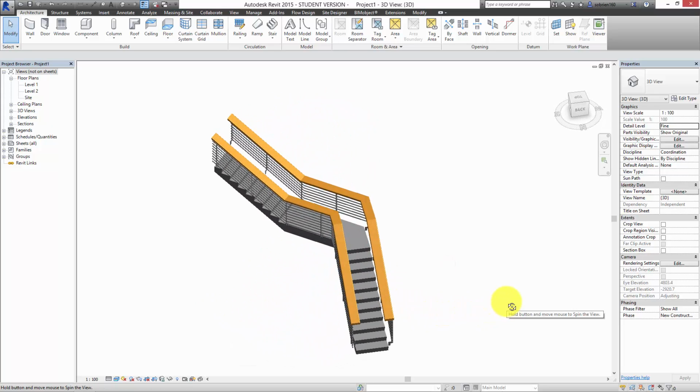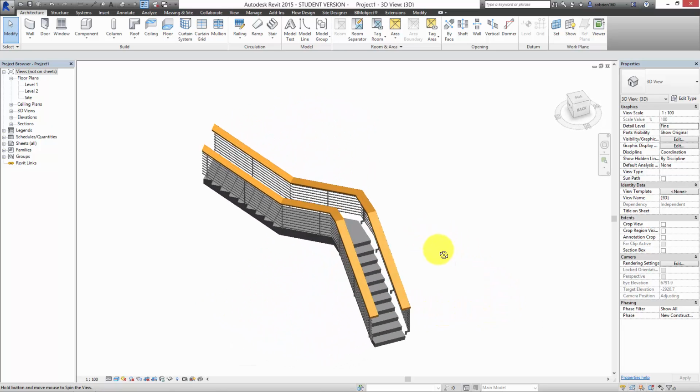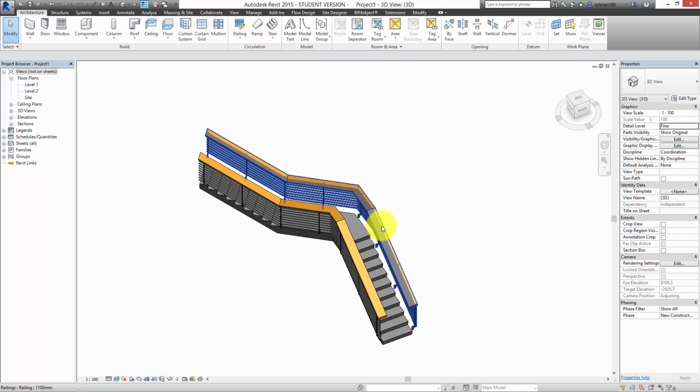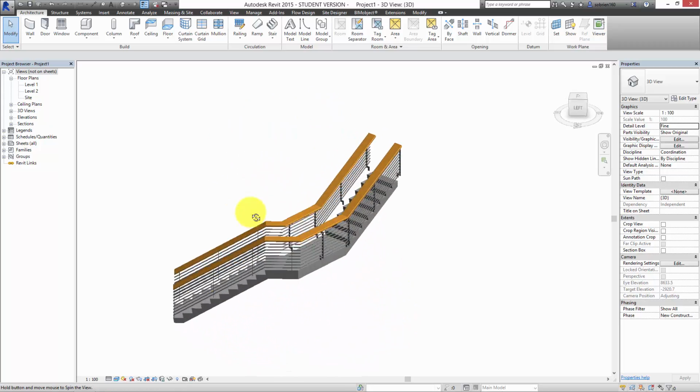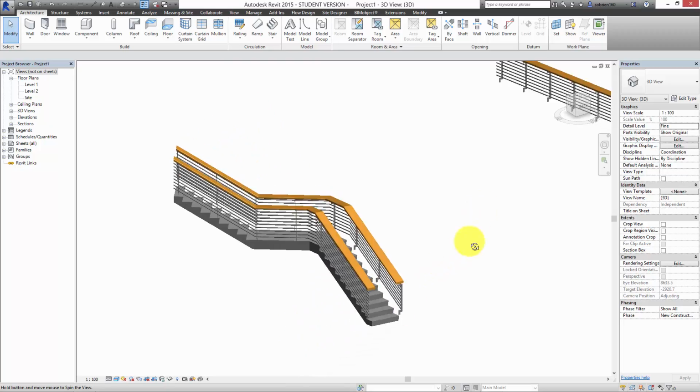Alright. Mine gives me, like, can create geometry for one or more rails. Yeah, it depends on how complex you've made the stairs. If you just say yes, it'll delete stuff it doesn't need. Often it's just warning you. Mine will delete the whole thing. Okay. Sometimes you have to play with it a little bit.